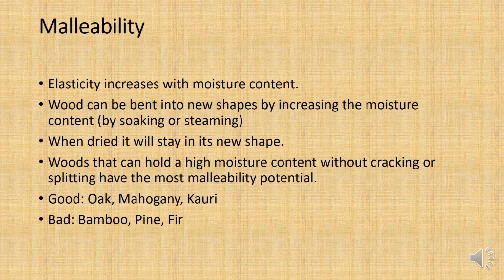And you need to be careful. You can't dry it too quickly, otherwise it will split. You need to have temperature control and everything to reduce the humidity over time, just like we talked about with the kiln dryers. Once it's dried, it's going to stay in its new shape. It's not going to bounce back into its original shape, because basically you've bent it under plastic deformation.